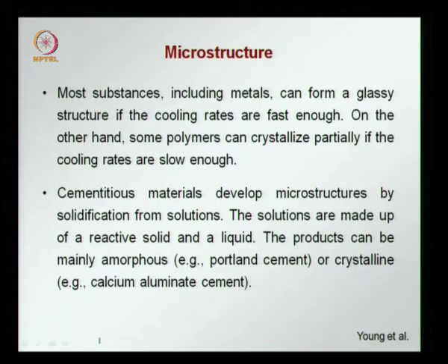We discussed also in the previous lectures that most materials, most substances including metals can be forced to form a glassy structure, an amorphous structure, if the cooling rate is fast enough. That is, there is not enough time for nucleation to occur, for the arrangement of the particles to form a crystalline structure. If the cooling rates are fast enough, you have a higher tendency for a glassy or amorphous structure to form.